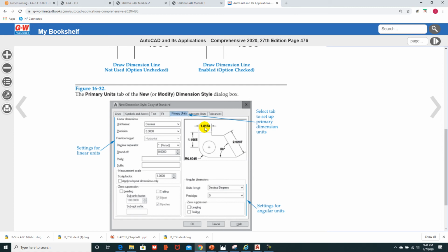For example, if we go to the third decimal place and you take a piece of paper and measure it, a piece of paper would be about 0.003, and you're going one more decimal place on this, so you're basically splitting that piece of paper 10 times to be able to get a measurement. Our aerospace companies do that, but these parts, something like this, would become very expensive as you start to work with that.